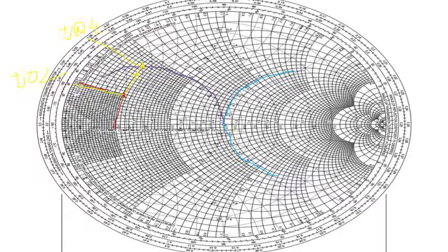But if it is a shunt connection, you will always take it as 1 upon Z0. So since it is a series inductor, omega L is equal to 0.2 into Z0. On solving, you will get the answer of capital L as 1.59 into 10 to the power minus 9 Henry, 1.59 nano Henry.